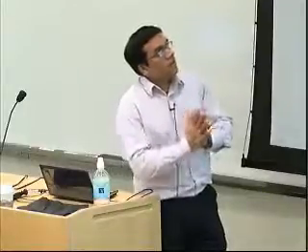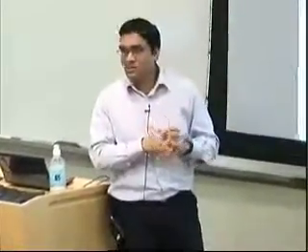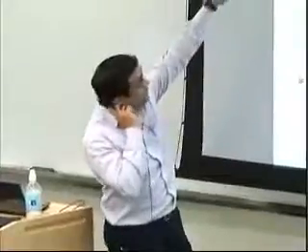Now let me talk about the coverage metrics for testing. Okay, and there are 3 coverage criteria. And the idea is that if you generate a set of tests that satisfy these 3 criteria, then that, along with the results of formal verification, is sufficient to prove trace equivalence. Okay, for any existence of an input-output interpretation function. All right, so let's go through this.